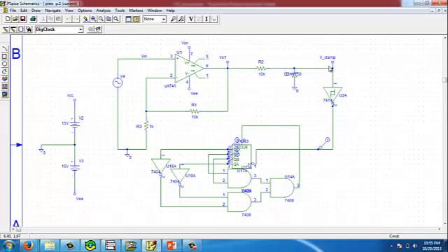Hence the output at V clamp which we obtained will be plus 5.6 volt to minus 0.7 volt. This is given to a Schmitt trigger whose output will be a square wave from 0 to 5 volt at 1 kHz. This is then given as an input to a clock signal of the 74393, which is a ripple counter. A counter is a device which stores the number of times a particular event or process has occurred in relationship to the clock signal.